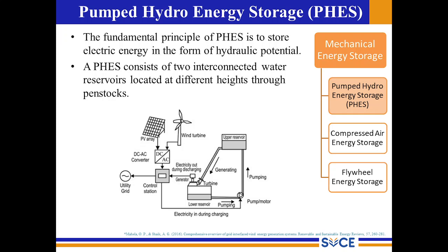So pumped hydro energy storage is also one of the oldest. If we see the system, you have a lower reservoir and an upper reservoir, which are connected through two different systems. One is your generating system, and the other is your pumping system. When you have energy in surplus, or energy at low cost, the water in the lower reservoir can be pumped by supplying this energy.